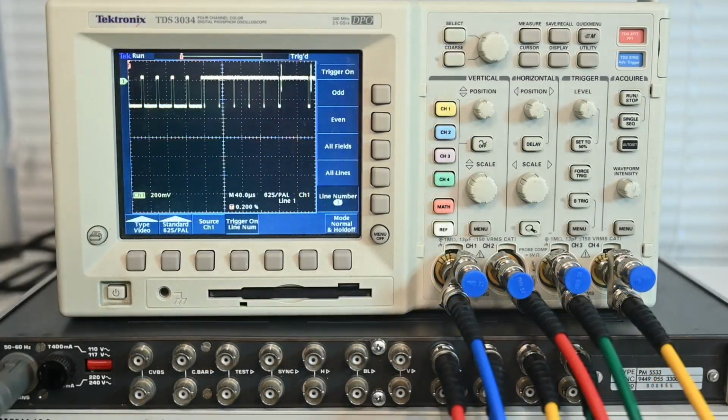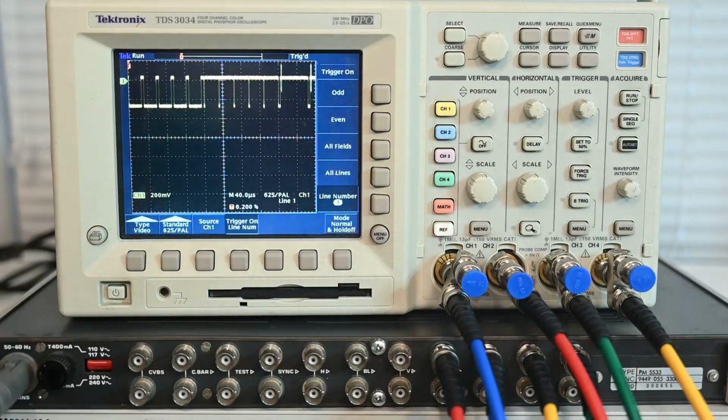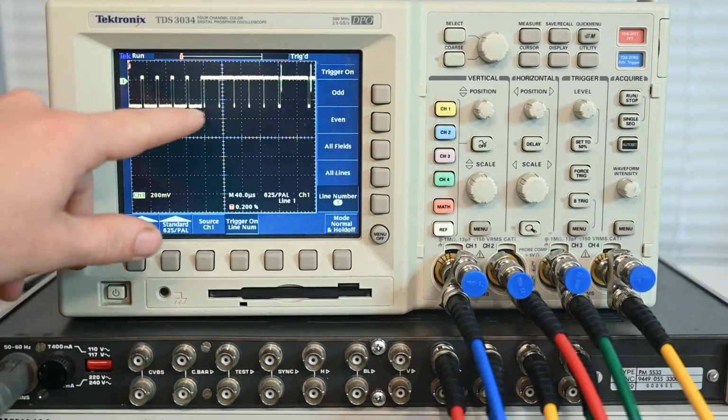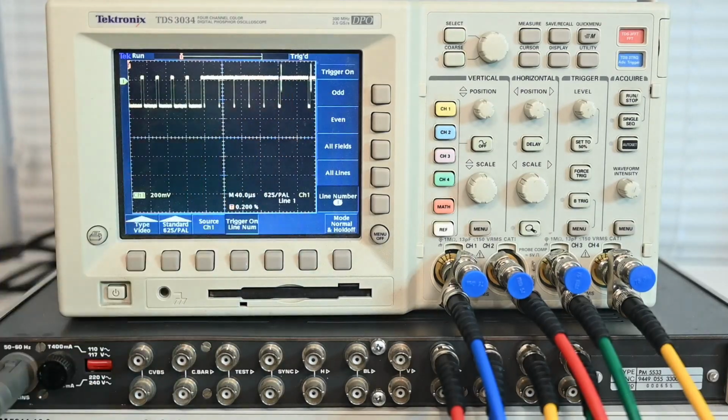Now for our color signals, we once again have 4 to look at, but it's 4 completely different signals this time, which I've hooked up to the oscilloscope here. I'm going to start off with the black burst, because I think this is just a signal which a lot of people are going to be familiar with. As I say, it is very similar to the mixed syncs. It really only differs by the fact that it has the color burst, and we can see it just starting to appear on those 2 lines there.